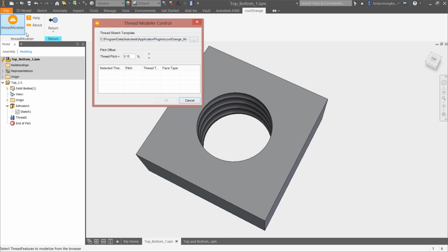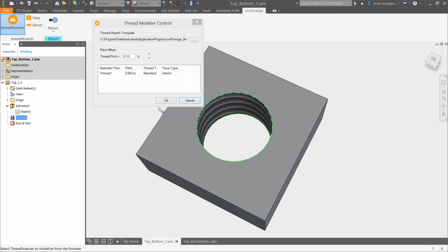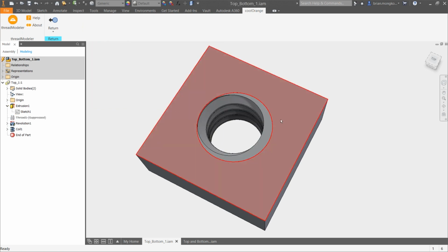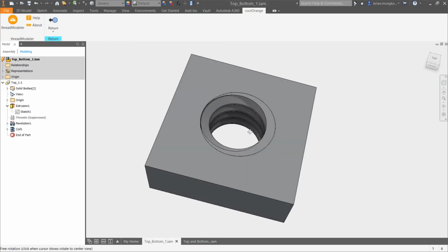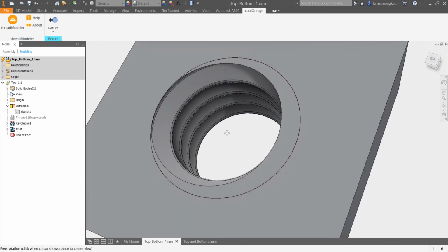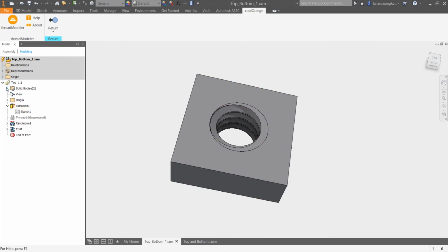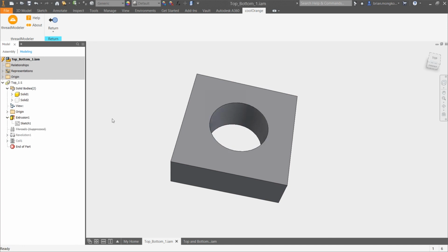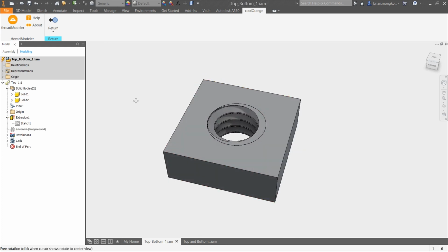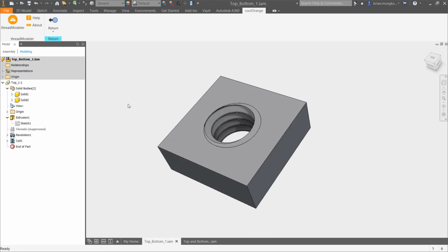So once you have that add-in ready to go, select the thread that you want to convert to a 3D model. Hit OK, and that's it. We have a 3D modeled thread that when you 3D print, it'll actually look like this. Just keep in mind that it does come in as another solid in the middle. So if I hide the visibility, this is what we originally started off with. So you can do maybe a combine maneuver before you export that out to your 3D printer.